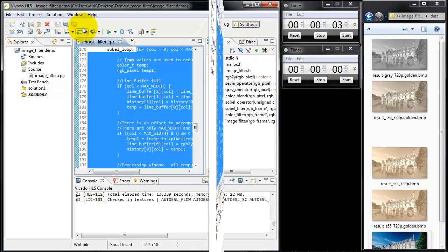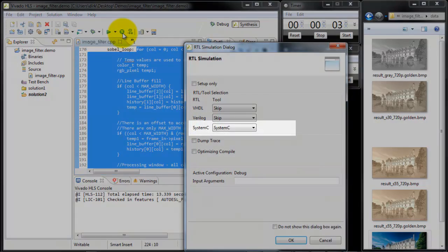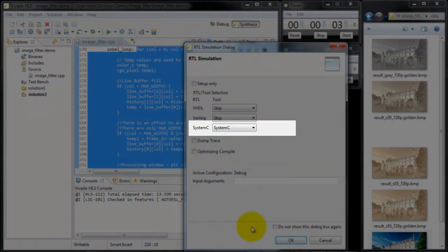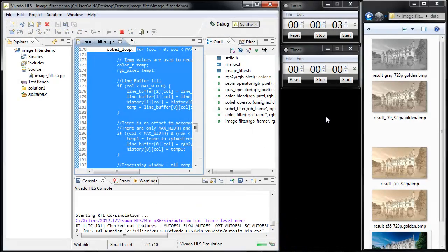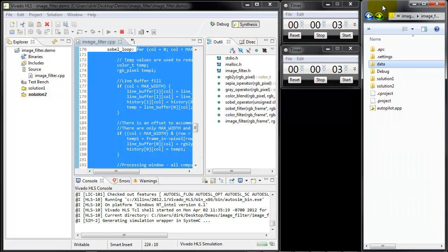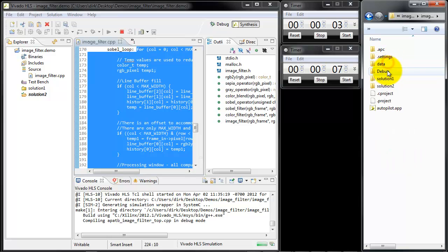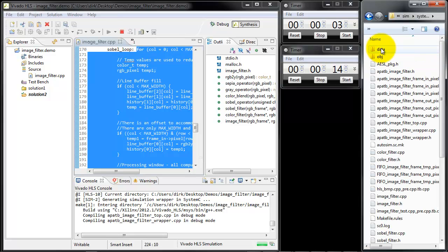This brings us to the next steps. Verify that the RTL works with the original C-based test bench, and package the RTL for bitstream implementation. For this demonstration, we picked the System C architecture result and co-simulate it with the original test bench. Since the simulation now has bit-accurate and cycle-accurate RTL transactions for the design, the test is going to take a long time. This illustrates even stronger why designing and fine-tuning at the C level provides such a productivity gain.